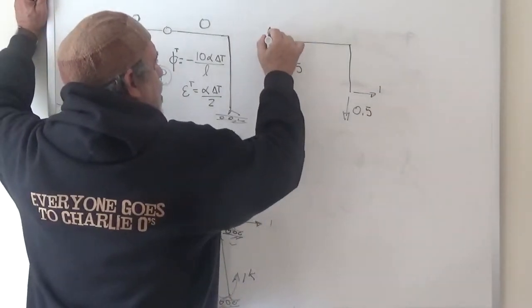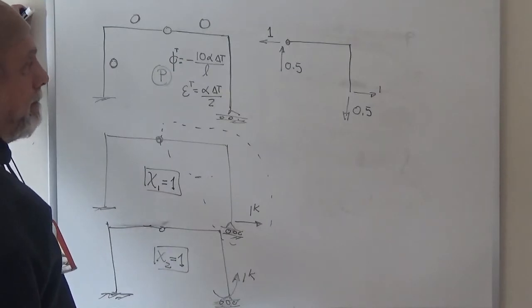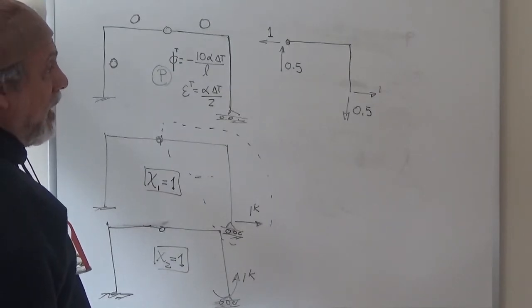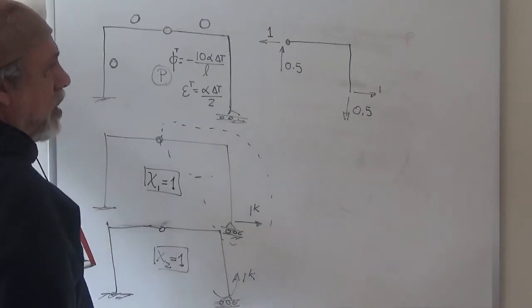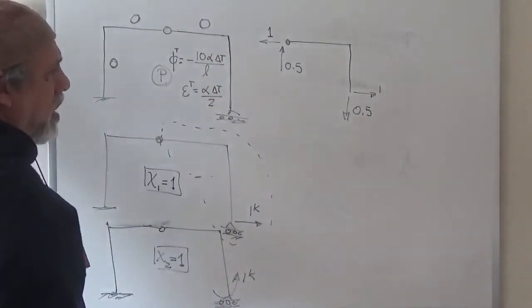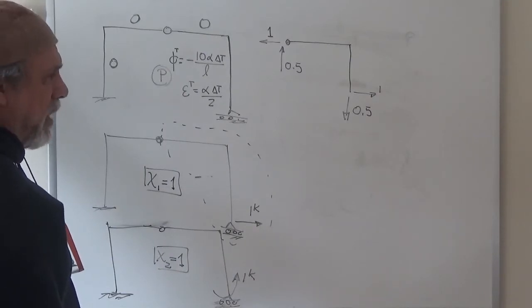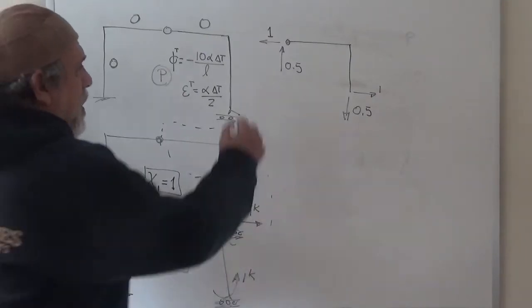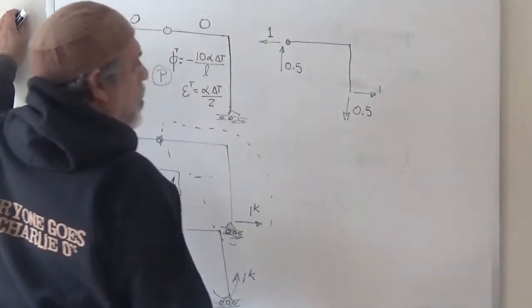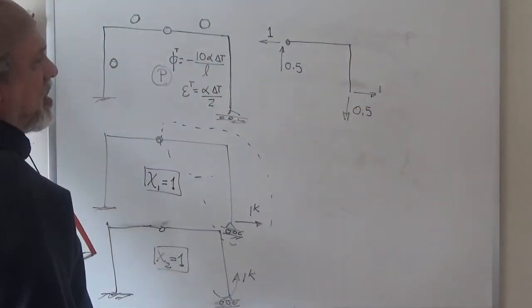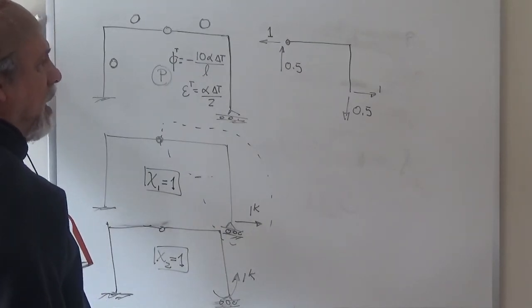Summing forces in the horizontal direction shows me that that force is 1. Now in your paper you don't need to be so frugal with writing equations. So write them down. Sum of the moments about 0 equal to 0, blah blah blah. Therefore this is this much, and so on. Sum of the forces in the y direction equal to 0, therefore this, and so on.